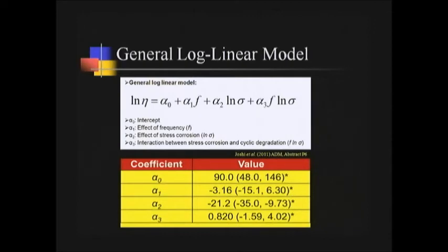And then looking at the coefficient for the third term, it has a confidence interval that overlaps 0 once again. And so for this material, we are not seeing an interaction between frequency and overstress, and we are not seeing a main effect of frequency for this material. Right now Yuan is conducting back home some studies on the Emax Zircad material, where we expect to see a frequency effect and an interaction with the overstress.